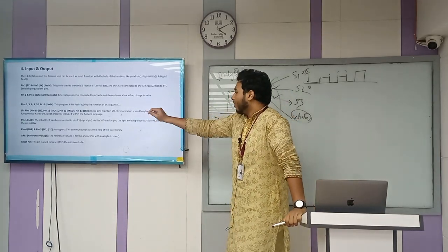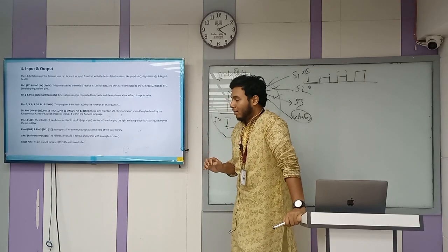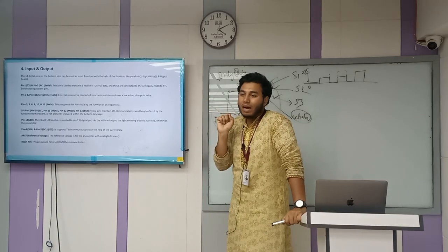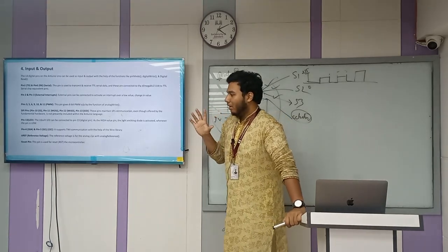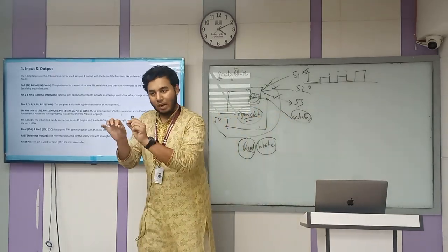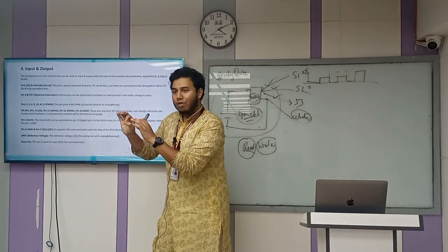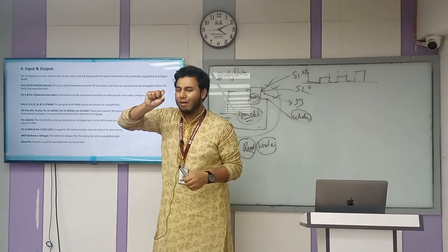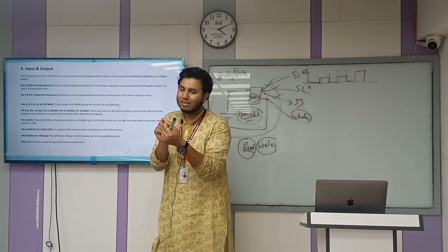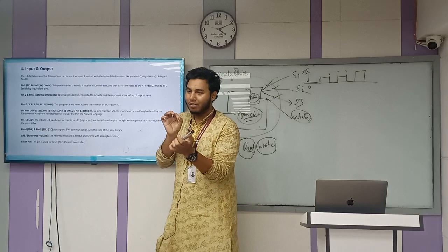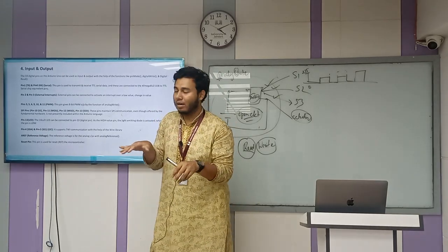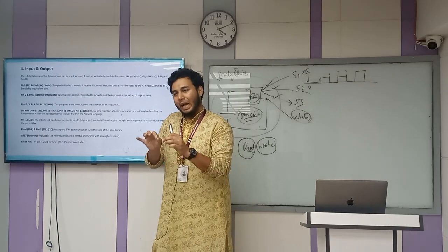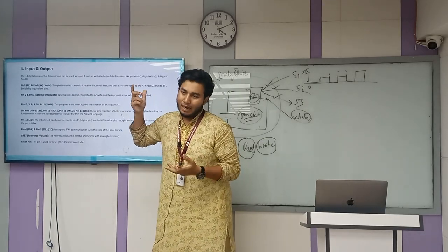If you look at pin number 13, LED, what does it have? The digital pin number 13 is a built-in pin of Arduino. If you want to connect an LED with the Arduino, you don't need to, because there is already a very small LED soldered onto the Arduino board, and you can blink it with a particular code, the same as an external LED.